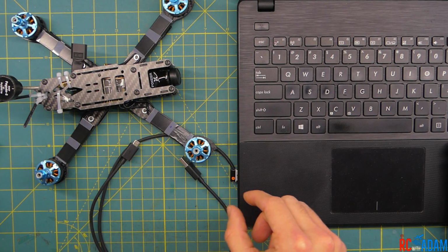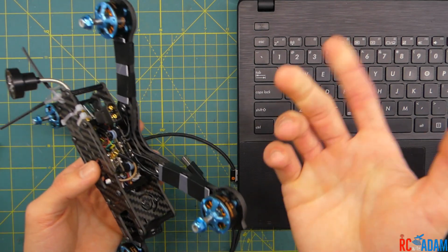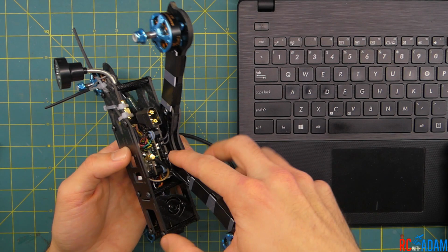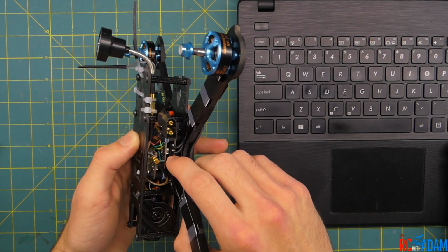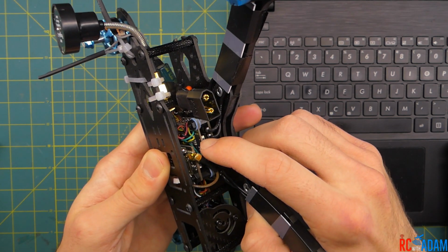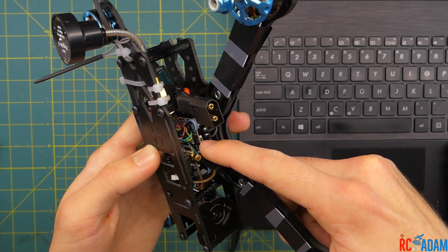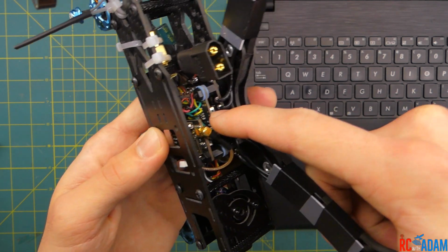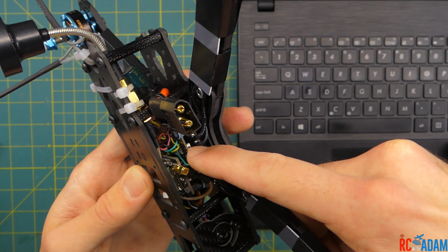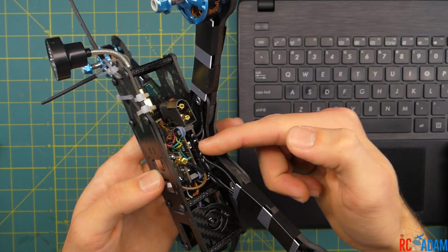So the first thing I want you to be aware of is that we're going to flash the flight controller, which basically means we're just going to do an update for the software or firmware, or whatever it's called. To do that, we have right here a bootloader button, and that's going to put it into bootloader mode, which just means it'll be ready to update. So we're going to hold down this little tiny button on the side of our flight controller board, and hold that down as we plug in our USB cable when we flash the flight controller.